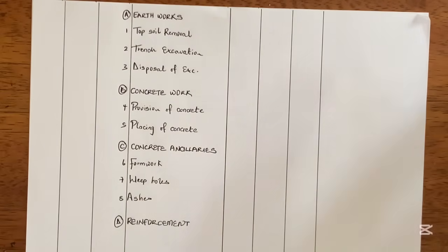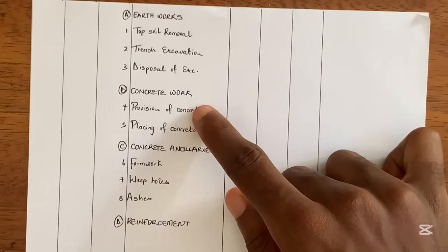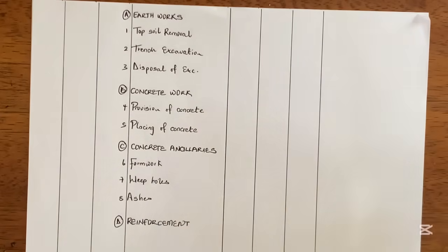If it were in building works, you know that we'll just measure the concrete once as in situ concrete. But now in civil engineering work, we have to measure for provision of concrete. This provision of concrete is to get the total volume of the concrete for all the structures that we are going to use for procurement, right? To tell them that okay, we need so much concrete.